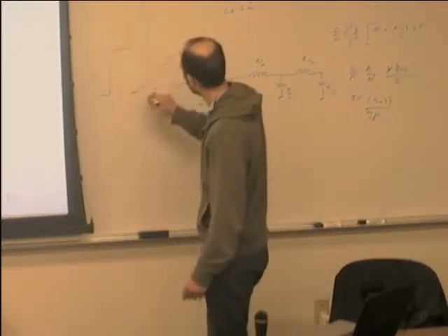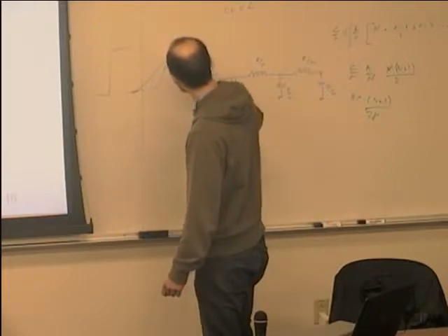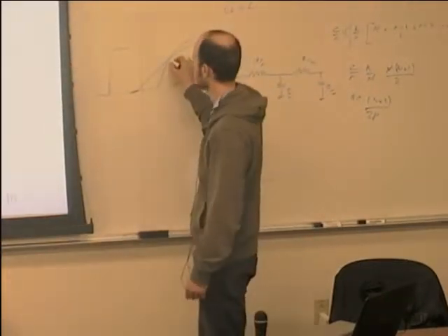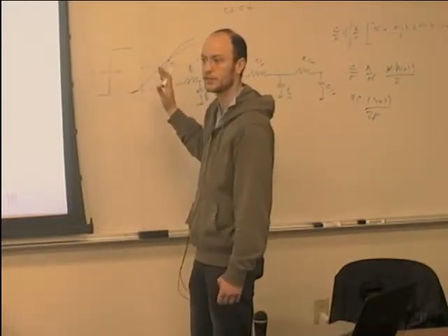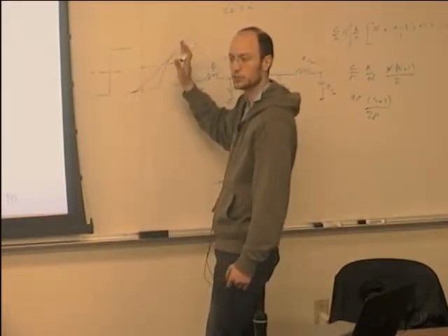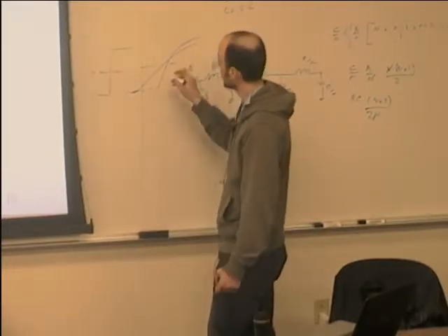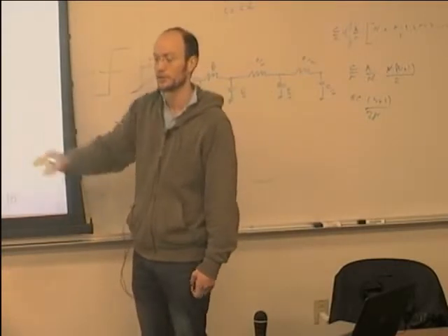And I guess this is not fair. The crossing point, as you go to higher order, remains the same, because all these networks have the same 50% to 50% delay. So the instant at which the output crosses the threshold will be the same. But the shape will change, and it will actually become less and less steep as you go to higher order.